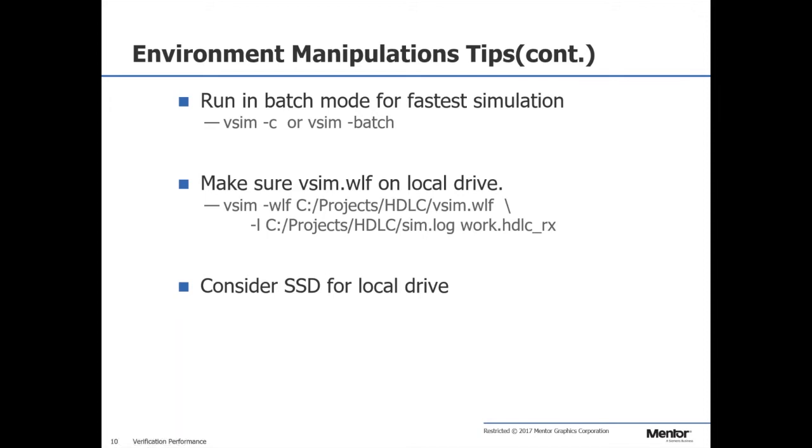You don't want network latency slowing down your simulation. So keep those two files local, if at all possible, and consider an SSD for your local drive, because that is often one of the things that slows things down the most, the writing of this WLF file.